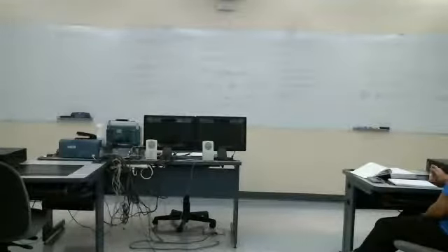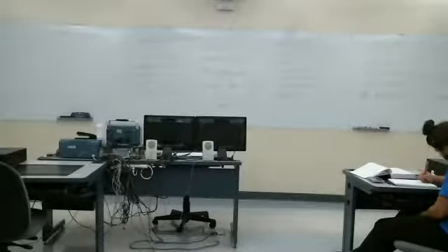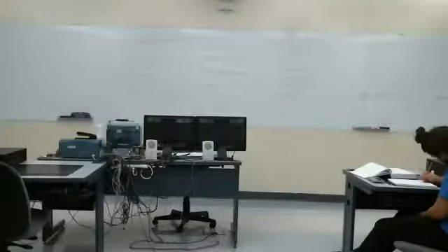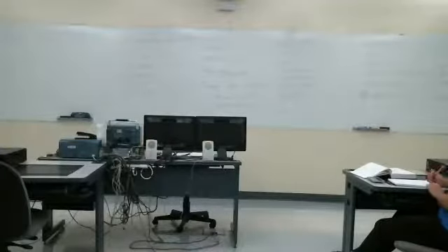Since differentiation and integration are actually linear operations, I'm not going to prove this, but remember the impulse is the derivative of the unit step. The impulse response is the derivative of the step response. So this would be one way to get the impulse response.